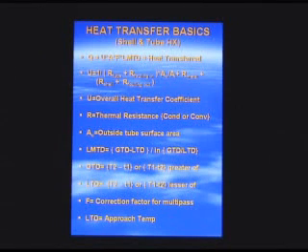And the tube side coefficient is based on the Reynolds number, Prandtl number, etc., to come up with correlations based on the type of fluid that we're dealing with, and the HTRI correlation will basically give us what that inside tube coefficient is. We've specified a fouling resistance either by TEMA or by industry standards or client preference.